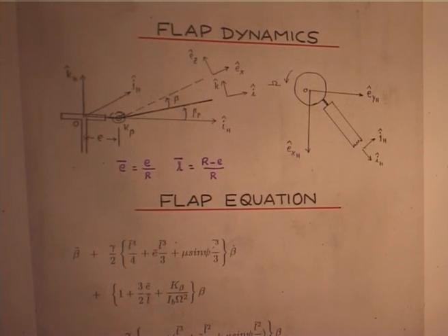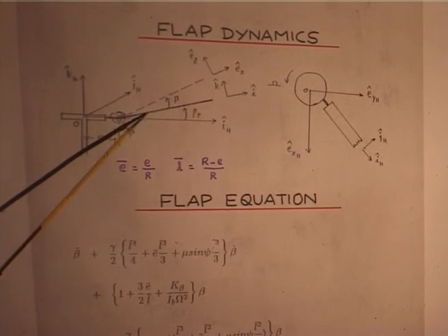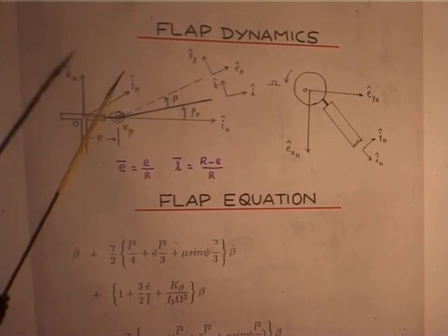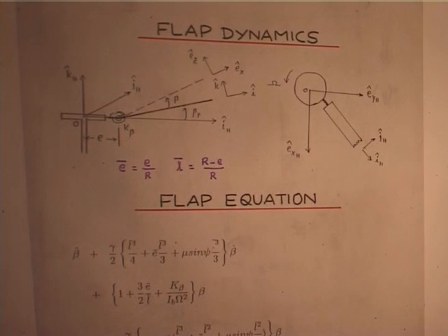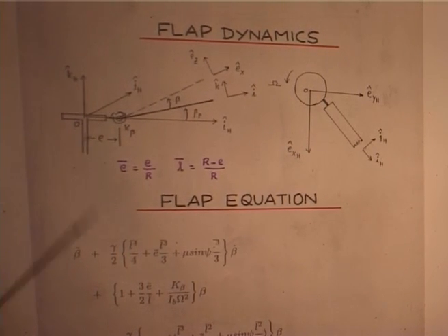Of course, the procedure is identical. I have given a precone, this is the undeformed axis, from there the blade deforms. So, take any point, find out its velocity, find out its acceleration, then take the inertia force, then balance the root moment about this point, because here is the root spring.